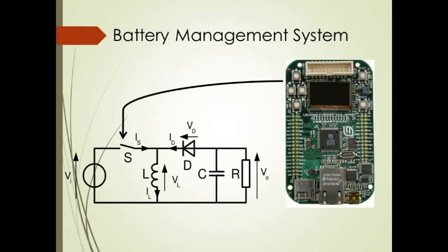As seen from the characteristics, the solar panel acts as a constant current source whose terminal voltage changes according to the load connected. By varying the duty cycle, Thevenin's resistance as seen from the solar panel can be controlled. Thus, with the optimum duty cycle, the operating point of the solar panel can be brought down to knee point. It is further noted that the power obtained from the solar panel is maximum at knee point.